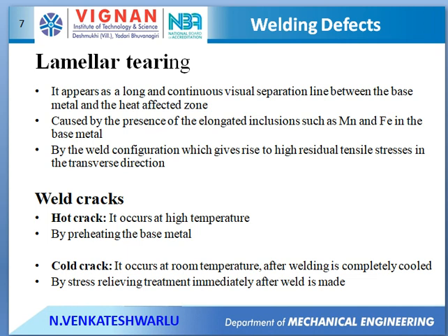So the next defect is weld cracks. We have two types of cracks, that is hot crack and cold crack. A hot crack occurs at high temperature at the start of the welding. A cold crack occurs at room temperature after complete solidification of the weld bead.